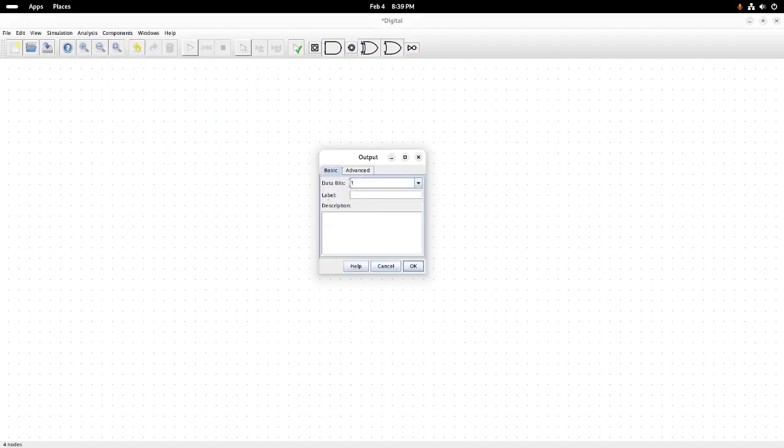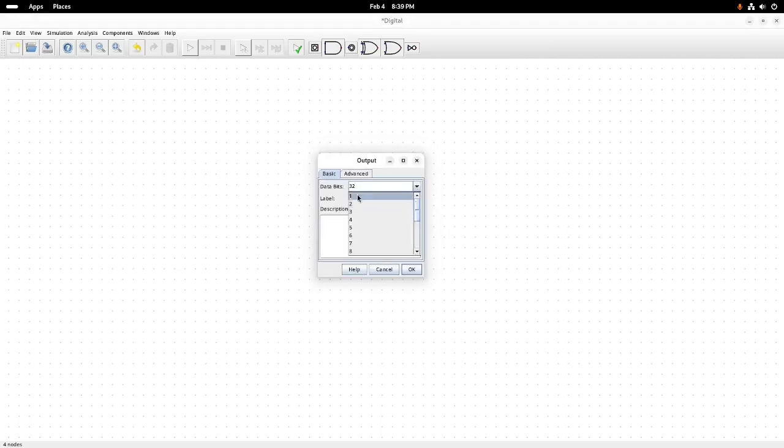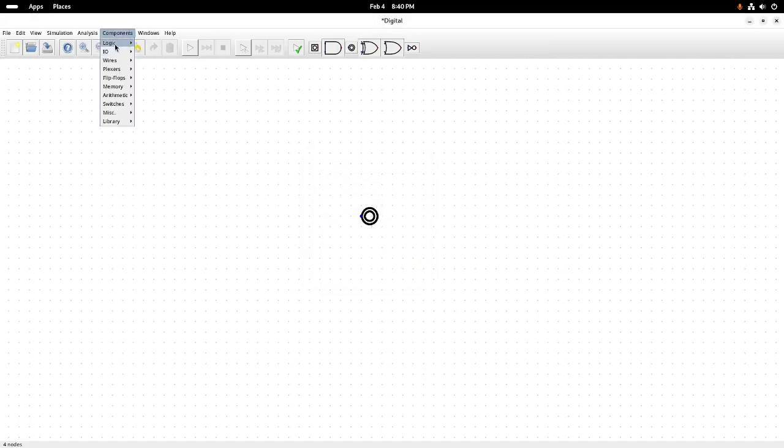These are cool because you can actually change the amount of data. So you can make data a bus where one wire represents 4 bits. It gives you a preselection of 8, but you can just type in 32 and it doesn't care. Now, the way it's displayed, you can actually change that. By default, I think it actually does hexadecimal. It's not binary. I know that for certain because, wait, let me change this to 4 bits. A little experiment here.